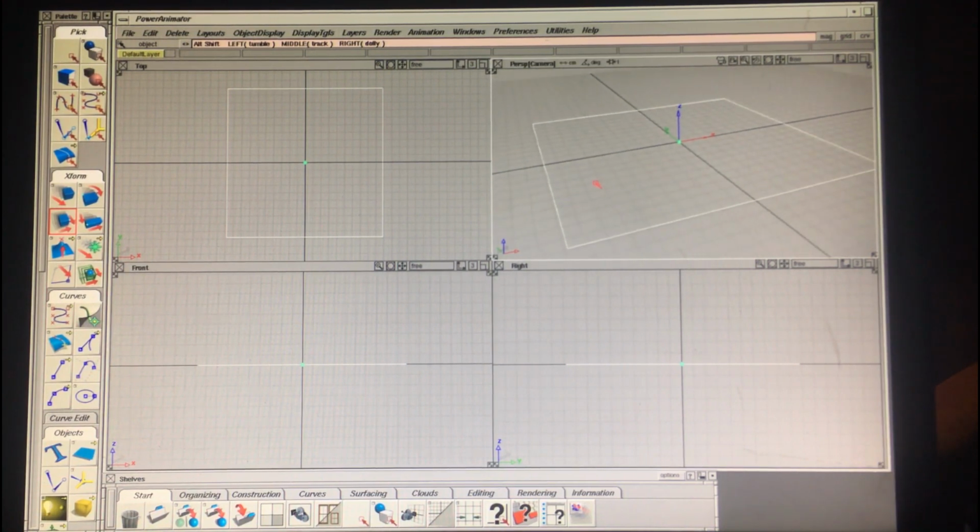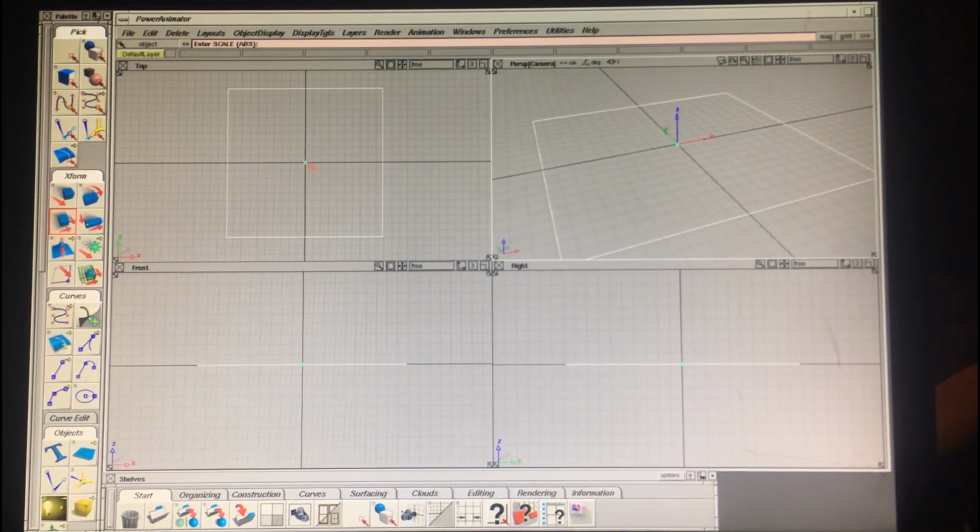And move this around. We have that. Okay, now we want to deselect. Now this is where I'm going to show you how to use the marking menu. So instead of using this to deselect up here, the pick no object, I'm going to show you the marking menus. The marking menus are the Control and Shift combined with left, middle, or right mouse button.